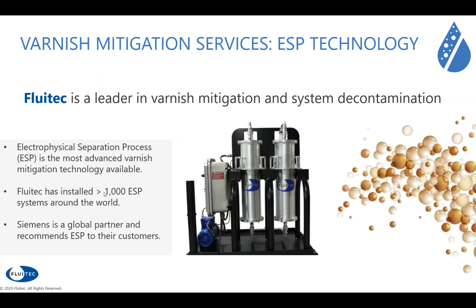So at Fluitec, based on all the research we have been doing in the field, we have developed a unique advanced varnish mitigation technology which is able to keep the oil clean. By doing this, it's clear that when the oil is clean, as the varnish deposit process is a reversible process, you're able to bring the varnish back into solution. And that is what we have been finding out and experiencing over, like you say, many hundreds of successful ESP systems on the market. And remember, for your confirmation, that this mitigation technology works on the warm in-service oil.